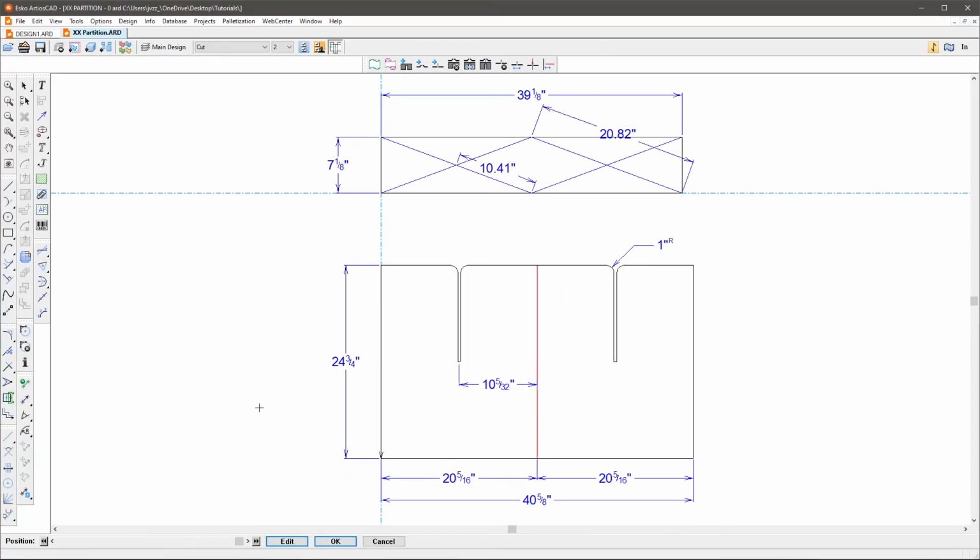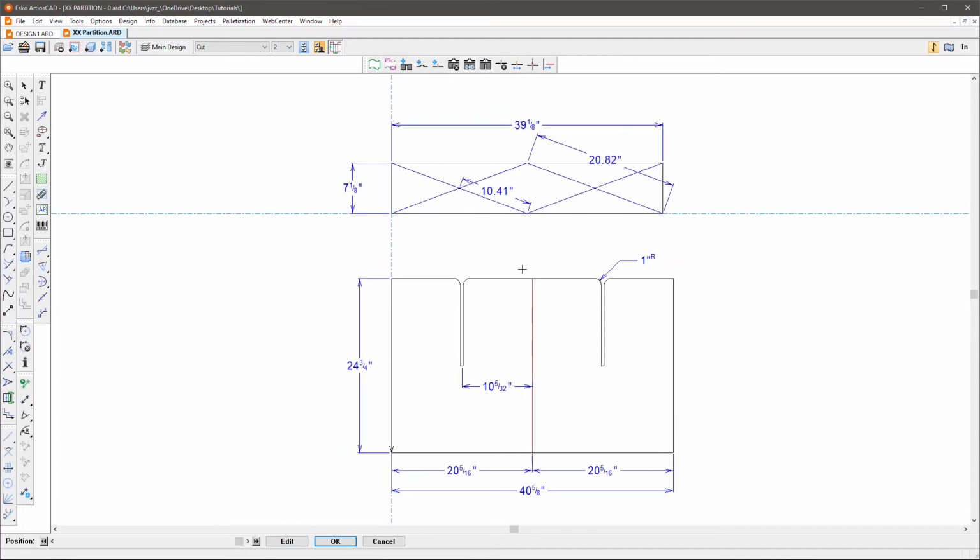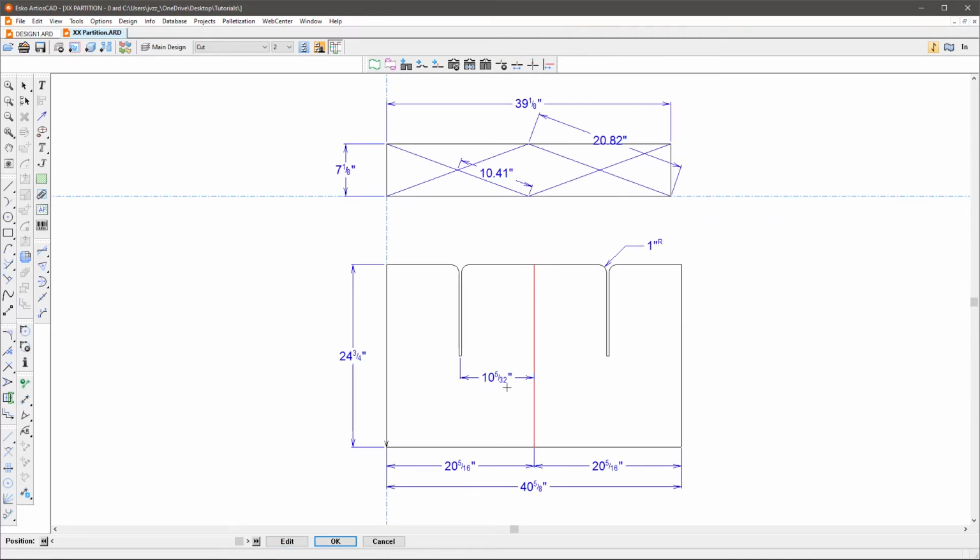Let's fast forward. And there we go. Now it's an even 16th. My sheet is an even 16th. And that was super easy. For future reference, if you have an Artios CAD design that you use a lot and that you're typically stretching or whatever to get it to fit, you could potentially make that into a parametric design and use it in your standards catalog.